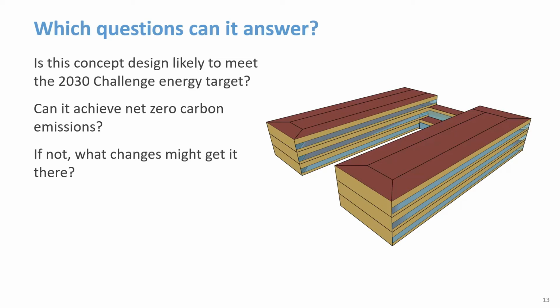One important thing to keep in mind when you're asking questions like these, where we want an estimate of the actual future energy consumption, is that a simple box model is quick and simple. And it'll probably be based on lots of assumptions about things like the HVAC system performance and the building operation. So at this stage, this energy estimate is best used for comparing alternatives and finding the best design solution. Then, as the design progresses, it'll be possible to get a more confident estimate of total energy consumption and to verify that the design is still on track to meet those performance goals.